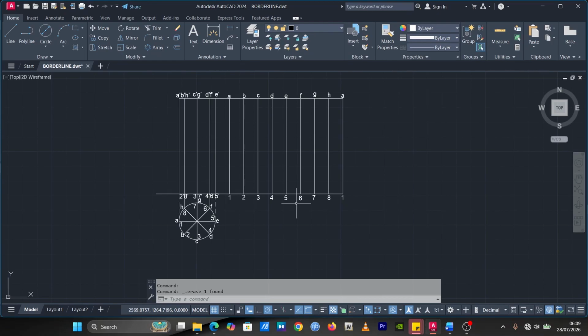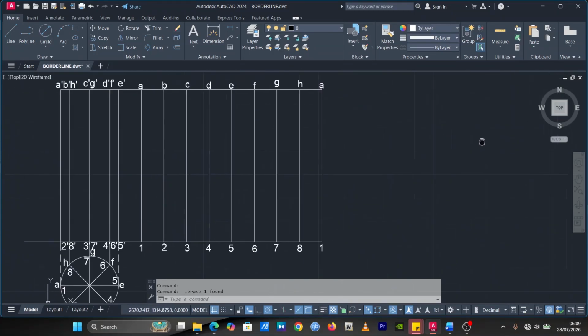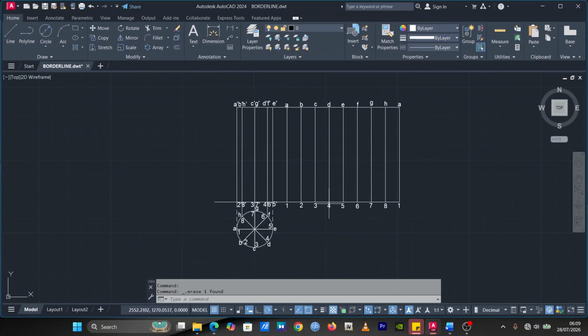Yes, so when we are done, we are going to draw our base. And in drawing our base, we are going to use the circle here. We project 1 here and we project 1 at the top. You can choose any of the numbers to stand and put the center of your circle to that number. But then let's say, assuming I choose 4, I'm going to assume practically that I folded it from this side to this side. But first of all, let's say I'm choosing 4. So let me finish drawing the base first and we move on.